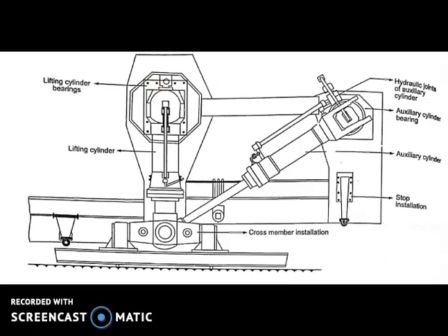As the hydraulic circuits are activated, pressurized fluid enters the lift cylinder, which forces the shoes to come in contact with the ground. As more fluid enters, the lift cylinder pistons are moved further downwards, which lifts the tub and base above the ground. At this point, the whole load of the machine is transferred to the ground through the shoes. Move forward.